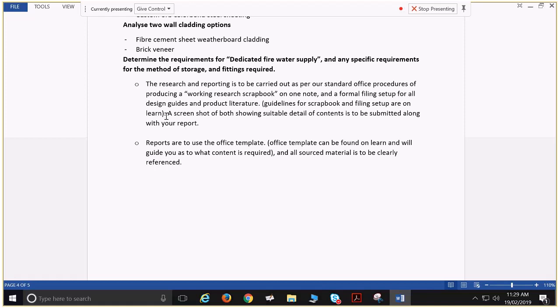But I'll take you through the process of finding out how much water we need to have on site for the CFS if they rock up at that building. And yes, it's a building in the metropolitan area. You'd think, oh, well, CFS, that's out there. Wherever we have a bushfire attack level that's above low, so we've got low, medium, and high, anything from medium, high, and flame zone, we have to have some water on site for the CFS.